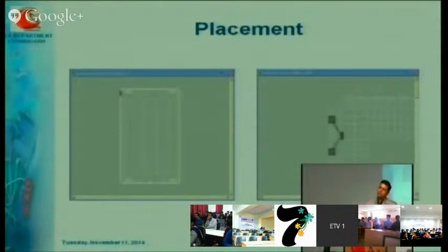Your software can place your circuit on any one of these floors, but the software has to check the optimal floor where your design will be optimally placed. Out of these floors, you have to select one, and normally this selection depends upon the IOs used in your design. Normally the software selects the floor that is closer to the IOs.